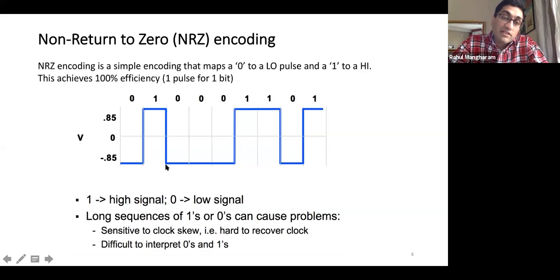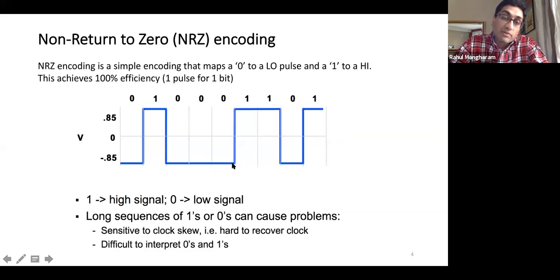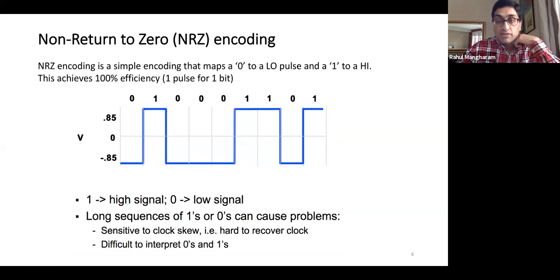That means the sender says, hey, this is beat 1, this is beat 2, this is beat 3, and beat 4 and beat 5, and the receiver says, yep, got it, we are totally in sync. But in many protocols, the sender and receiver are obviously operating on different clock crystals, and they're operating separately from each other. They're operating at a distance. One could be in a hot location, one could be in a cold location. So their crystal could be going slightly faster than the other.